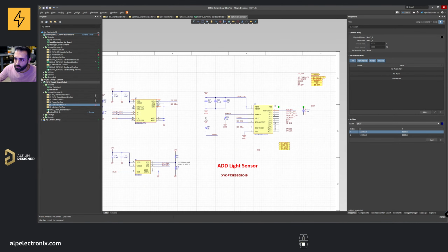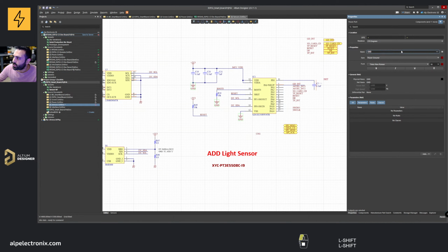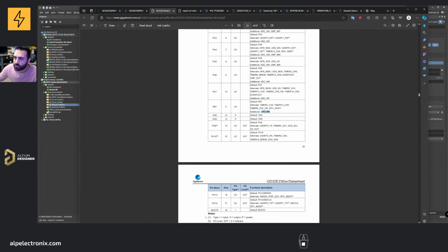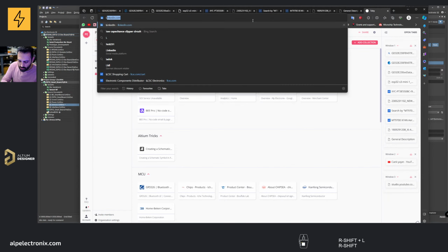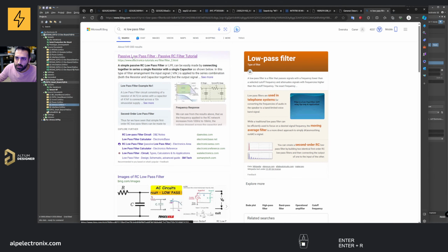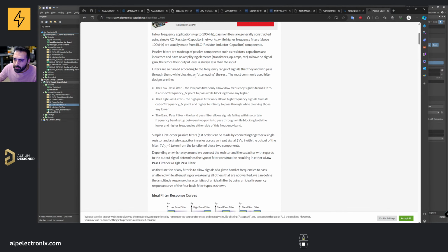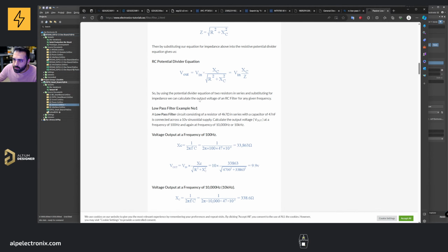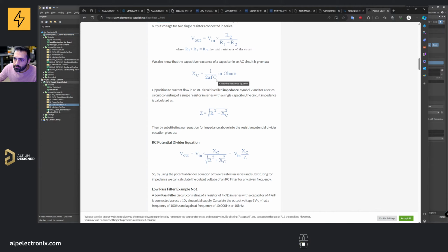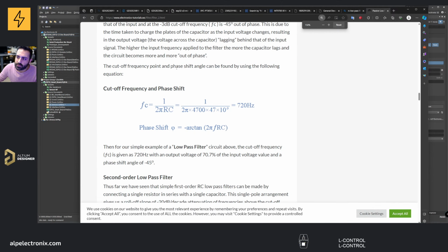And then we have this ground problem here too. You see, there are different grounds, and it will create a conflict. So I press Shift and select all of them together, and correct it. For the low pass filter, I know the formula, but just to show you, the RC low pass filter: you need to set the capacitor and resistance values and the cutoff frequency, FC. Basically this is the rule, guys.